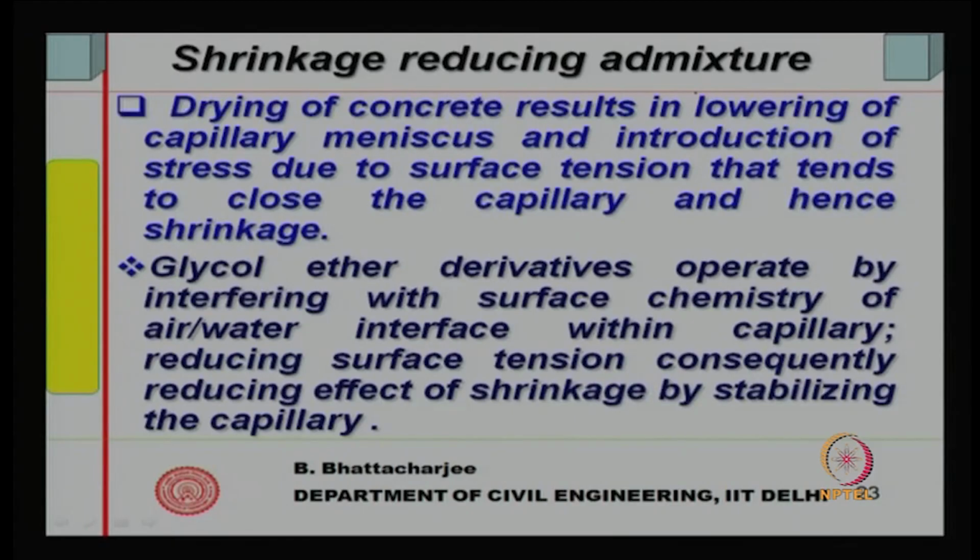Because it was at a balanced condition and now it has lowered because some drying has occurred, there will be surface tension forces that tend to close the capillary and hence shrinkage. So, the capillary will try to collapse under these surface tension forces.